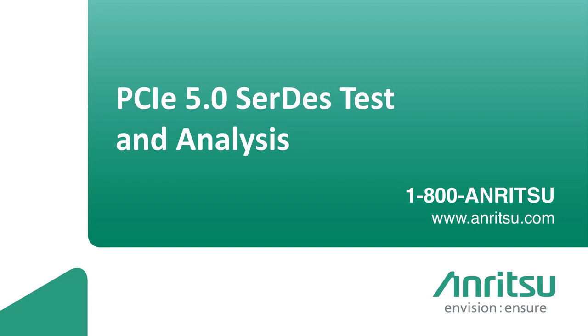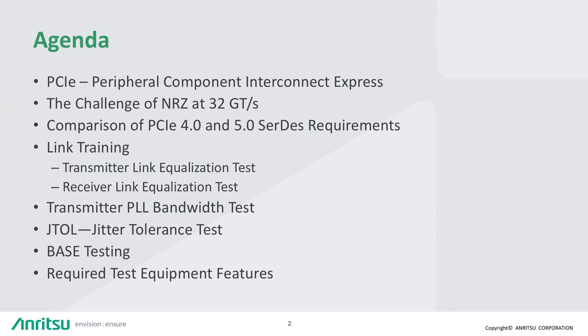In this webinar, we're going to discuss PCIe Generation 5.0 SerDes test and analysis. We'll begin with a short discussion of Peripheral Component Interconnect Express, which is what PCIe stands for. We'll move to the challenges involved in transmitting non-return to zero, that standard baseband logic scheme that we've been using all our lives, at 32 gigatransfers per second.